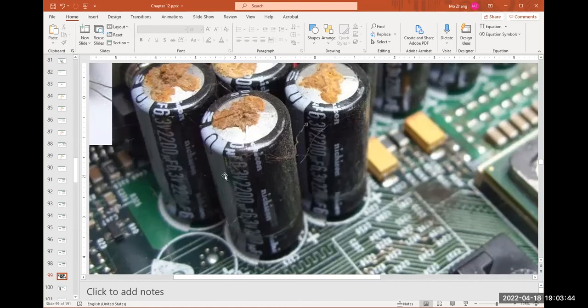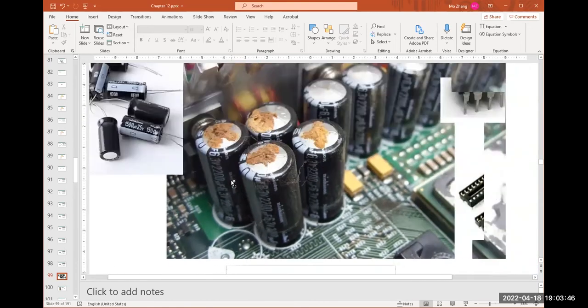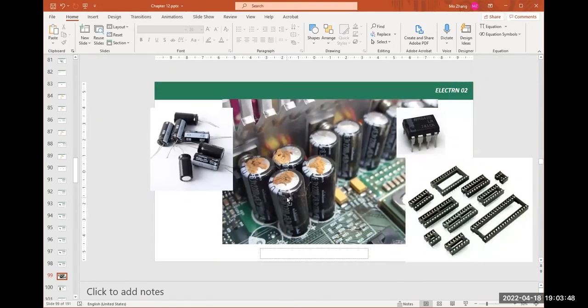Then enter this number on eBay, Mouser.com, Amazon, Alibaba, Taobao, whatever, and find the equivalent one. Once you get it, insert the newly received capacitor back into the board, solder it, and trim the extra wires. They should work, or at least this part of the circuit works.